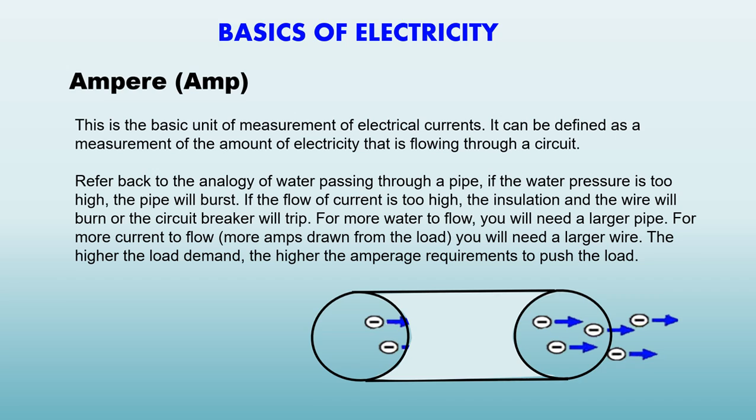Have you ever used an extension cord working some type of motor device, pressure washer, or saws, and when you go to unplug it, you feel that the wire is hot? One of the reasons is it's drawing more electric current through the wire than the wire can afford to send through it. It is starting to overheat.